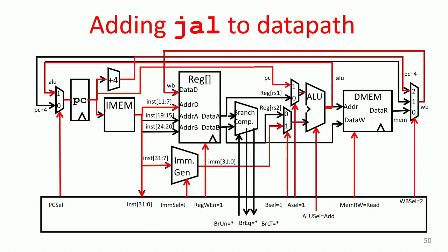In this case, the big change is we have this mux where we choose PC plus 4, put that into a register file as we did previously, and then program counter gets this upper input, which is the output of the ALU. The ALU, this multiplexer gets a PC value, and we add the offset to it here, and that goes back around into the PC, right?